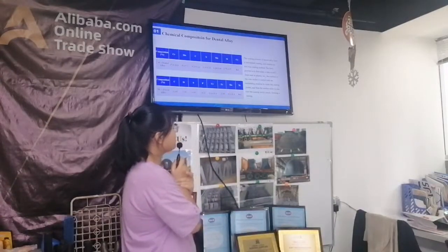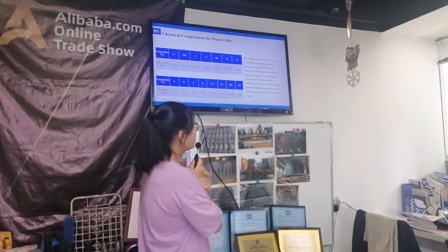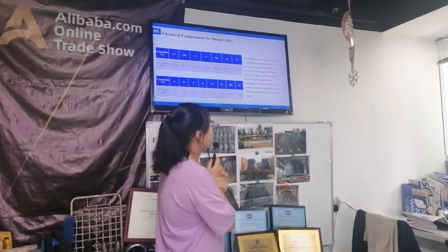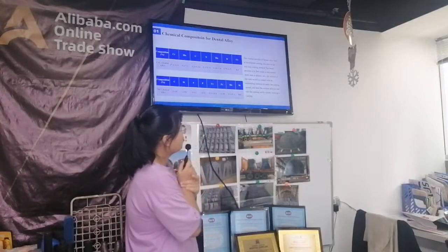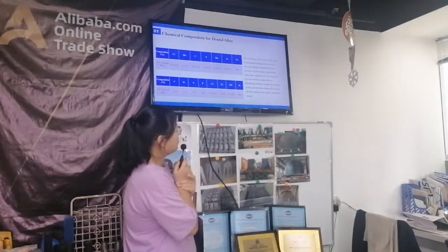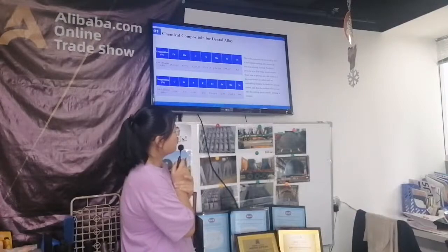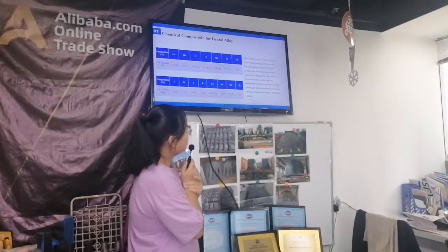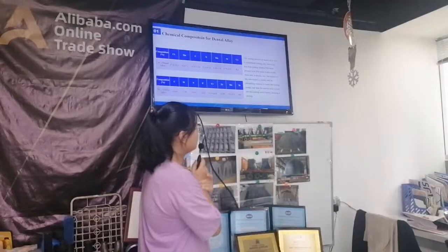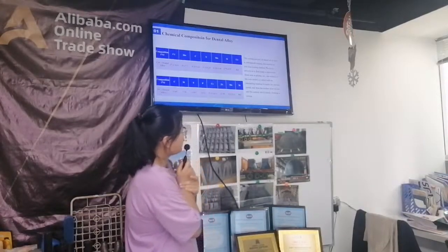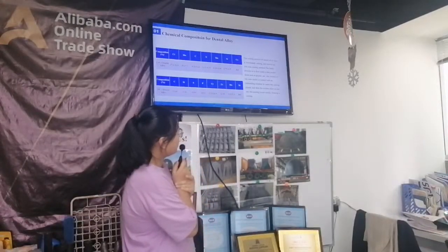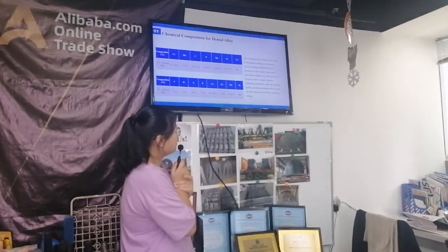The casting process of dental alloy parts is investment casting, also known as lost-wax casting method. The basic process is to first make a wax mold from wax or plastic. The surface of the wax mold is coated with an embedding material to make the casting mold. And then the molten alloy is cast into the casting cavity inside, forming a casting.